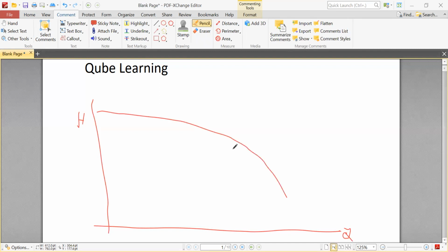And the system curve will increase: the head will increase when the capacity increases too, like this. And the pump operation will be here. So this is the preferable zone where your pump will operate.